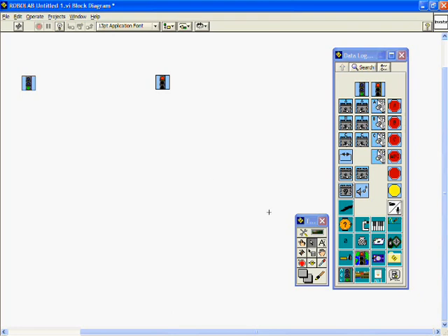One useful tool is the Automatic Tool Selection. This is the largest tool in your toolbox. Highlight it. Now notice as you hover over an icon, it becomes the Position, Size, and Select tool. As you hover over the port, it becomes the Connect Wire tool. And now you can connect two icons together. Hovering over the wire, it becomes the Position, Size, and Select tool again. You can highlight and then delete.